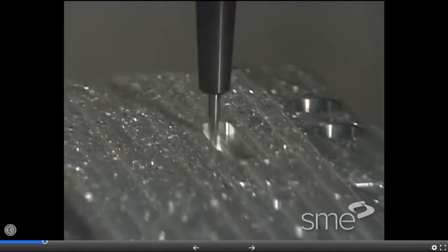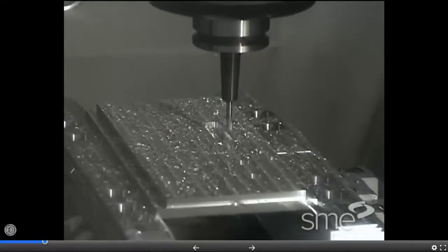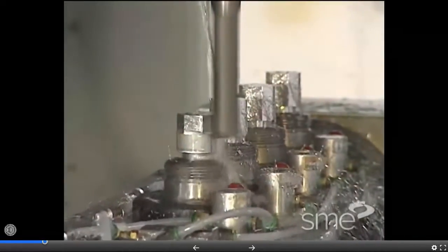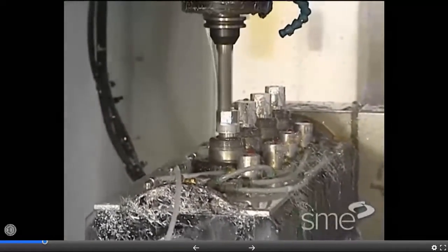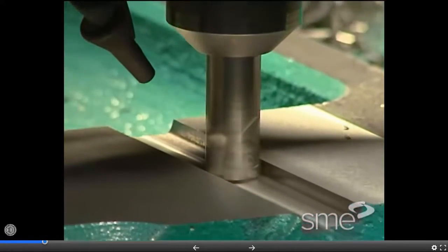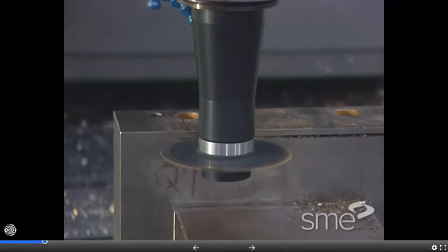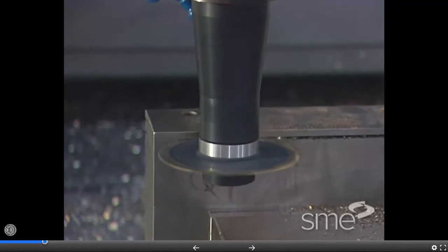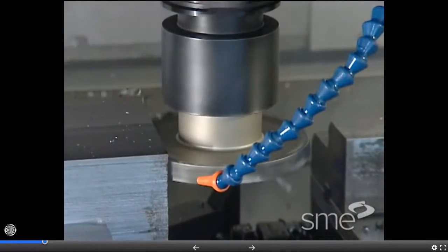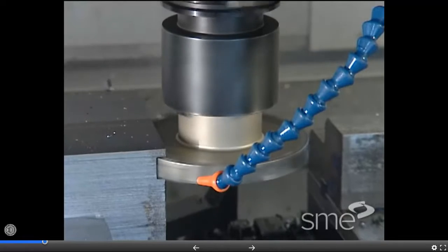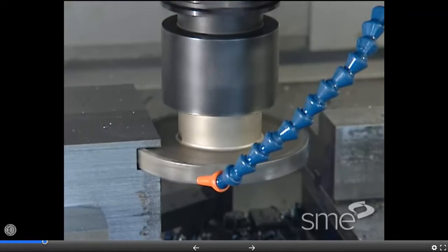Since end mills cut more with the teeth on their periphery than with the teeth at their end, they are susceptible to lateral forces. This makes them subject to deflection, which reduces the accuracy of the milling operation. Short, shallow slots are often created with end mills. Deep, narrow slots may be milled with an end mill, a thin slitting cutter, or a grooving cutter. Grooving or slotting cutters are generally more efficient than end mills for cutting long and deep slots because of their larger diameter and greater number of teeth.